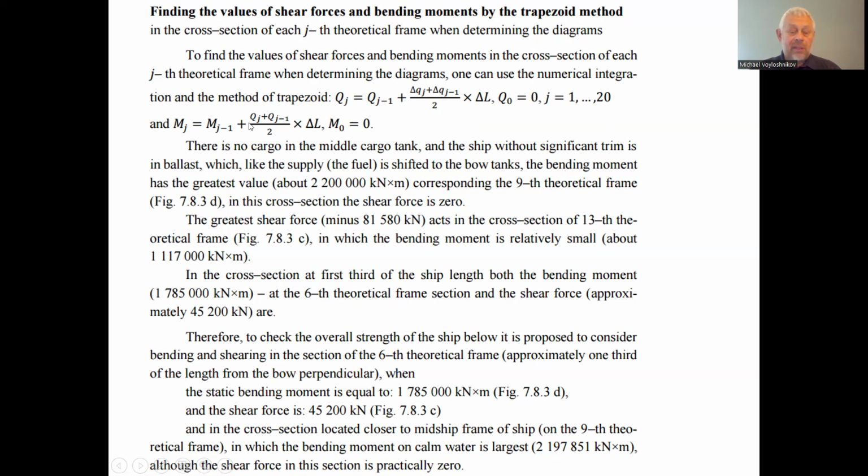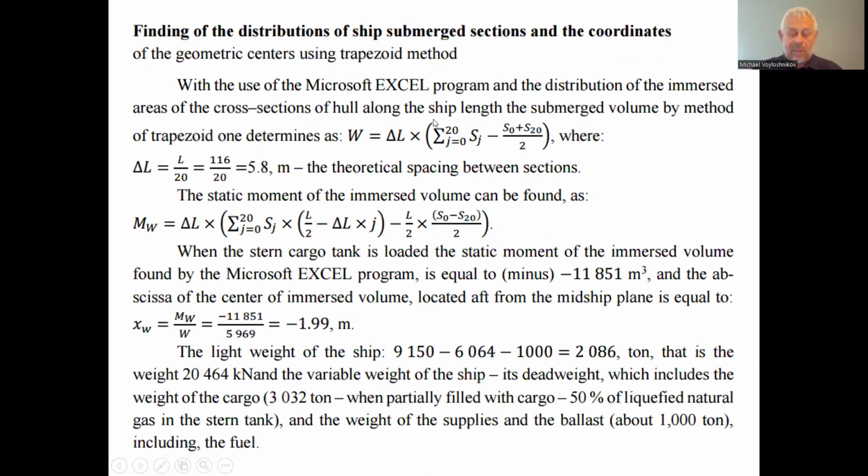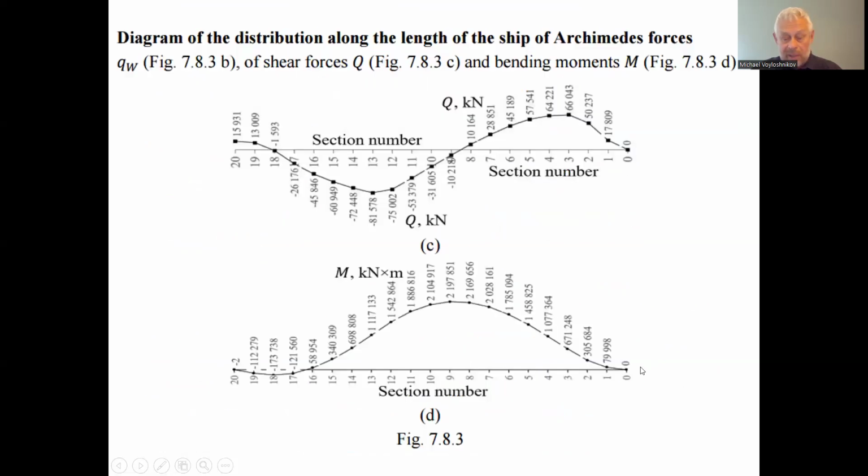And the bending moment is integral function due to the distribution of the transverse forces. So we have each next magnitude of the transverse force as the previous magnitude, starting from 0. For example, we can start here from 0 transverse force, moment from 0, because at peak we have 0.